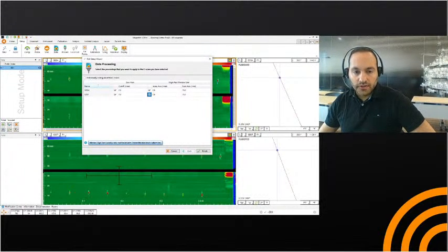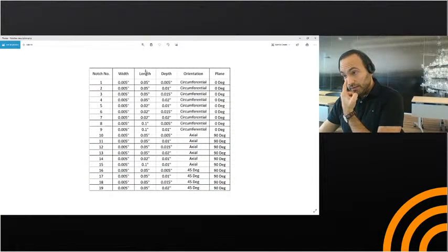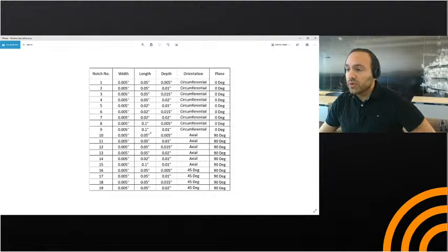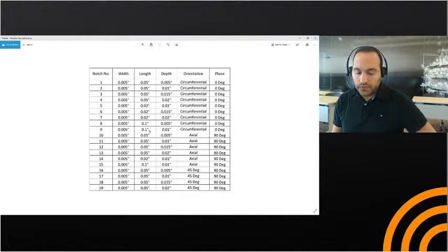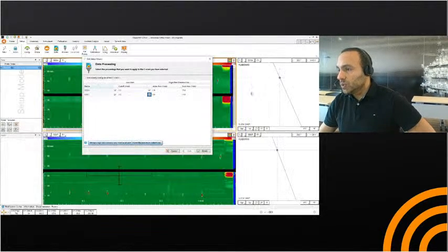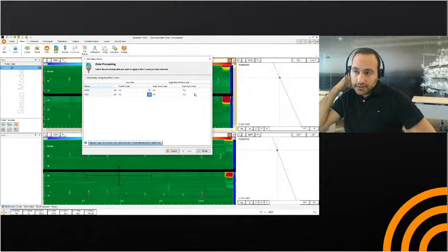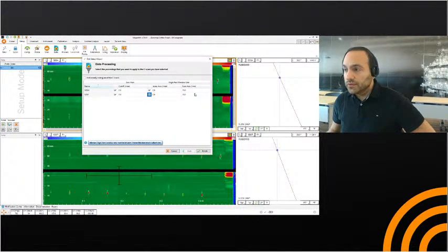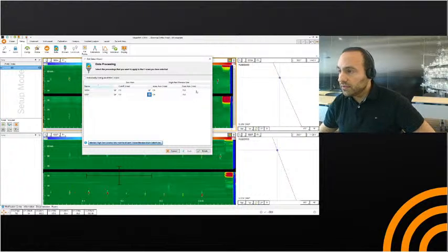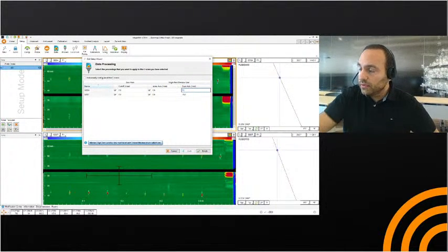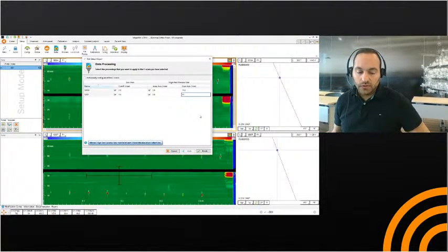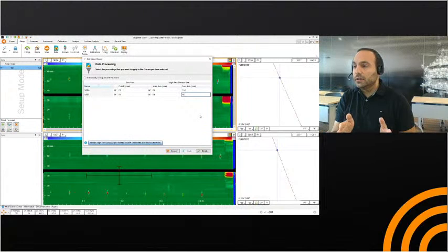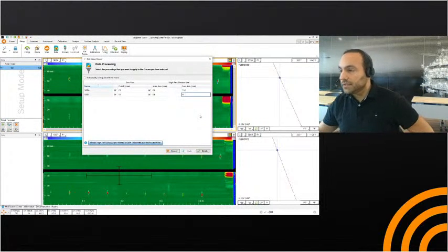So if I switch back to see, my longest defect here, I can see that it's point 1 inch. So this is approximately 2.5 millimeter. So at the minimum I can put is approximately 7.2. So just to make sure that this is not too tight, I will put 15 millimeters. So here you should always make sure you won't cut any signal coming from your target defects.